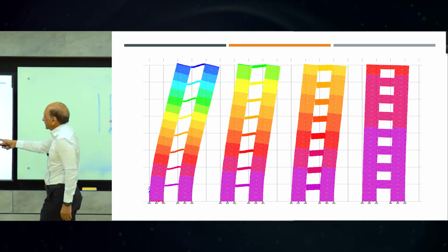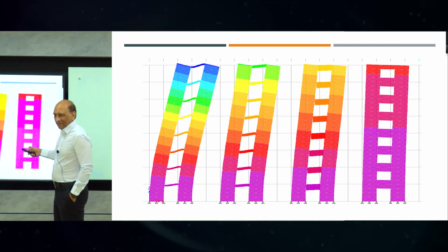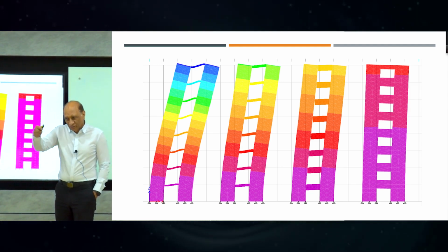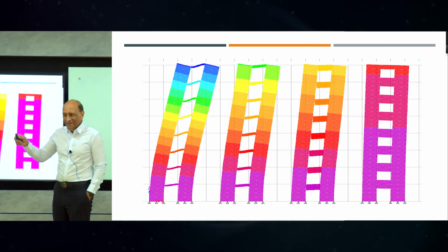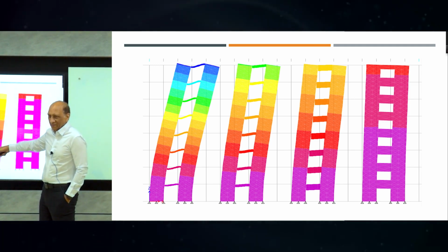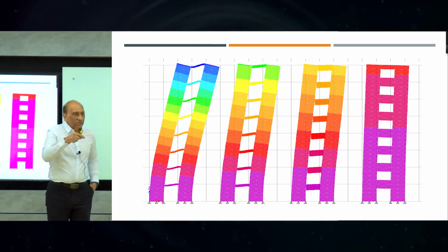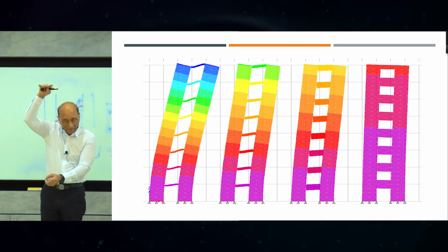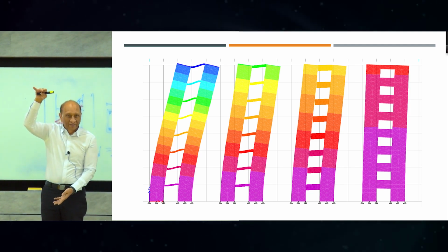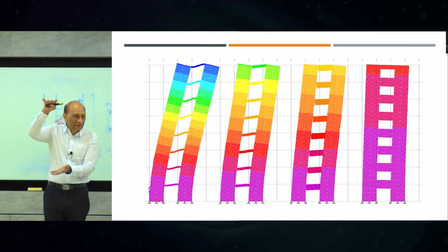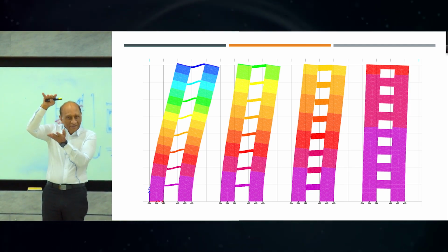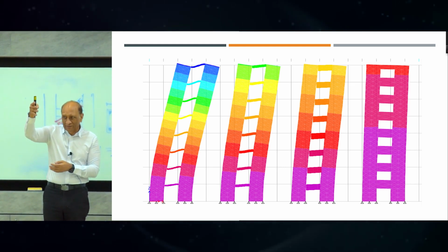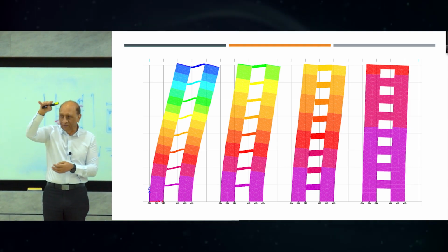So that is one thing. The problem is that the forces in this one will become very large. Then you will run into this trouble that it will fail in shear. And then you have to make sure that it doesn't do that. So you go back and go to something like this. Okay. So that's why the size of the link is normally fixed by architecture. You cannot change it because of the head clearance and all, and the floor height. So you cannot increase the size by yourself if the shear increases. So if the size is fixed, that means shear capacity is fixed. If the shear capacity is fixed, you fix the moment by putting the reinforcement, which is not beyond that.